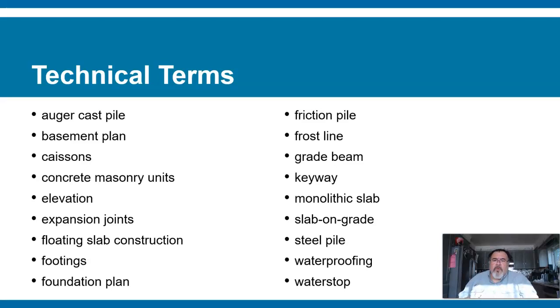So one thing you want to remember is that a particular design, a foundation, is pretty much the same shape. It's just that this particular shape travels a distance that's usually measured in lineal feet. So when you look at a cross section of a detail of a foundation footing, you'll see that there's a footing, a stem wall, and then within that you'll see the steel that's embedded within the concrete that represents that foundation wall, either stem wall or larger retaining walls.